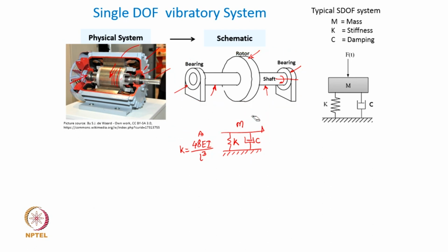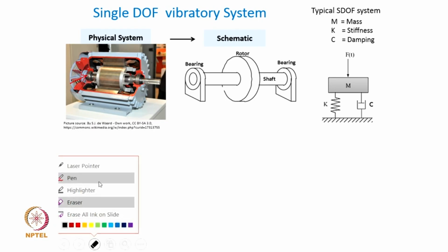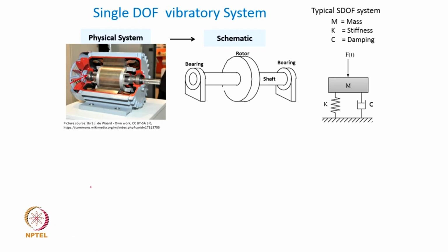Now, this is all with our understanding and our knowledge of this particular system, that we are saying that the shaft is treated as the most flexible element in this particular case. But you may as well see, and someone may question, that the shaft appears to be reasonably small in length, and have we checked whether really the bearings here are that rigid that we should treat the bearings to be rigid enough and the shaft is flexible enough.